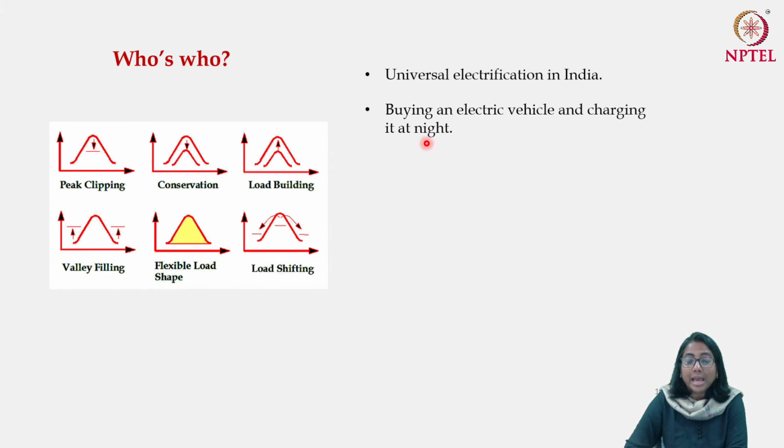Now if, assuming that night time is your off-peak period, you carry on this activity in the off-peak period, then you are contributing to valley filling, so that the rest of your load curve remains unchanged, whereas you are actually increasing your energy demand during the off-peak period.